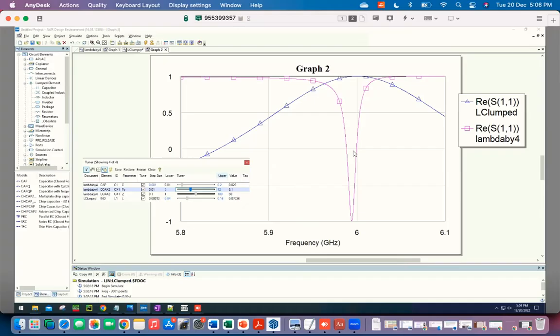Let me draw what it would look like. So let's consider microstrip geometry, right? A transmission line in a microstrip geometry is just a strip. You have to imagine this on top of a dielectric. It's ground. On the right side, I want an open. So how do I make an open? I just leave it. Even though it's not always ideal, that's the best you can do.